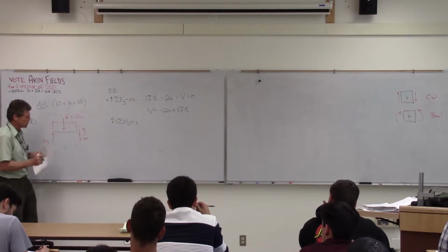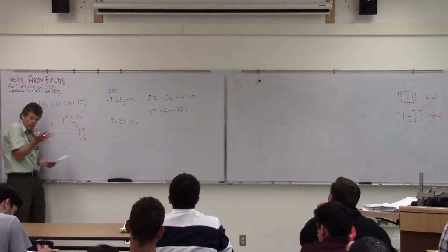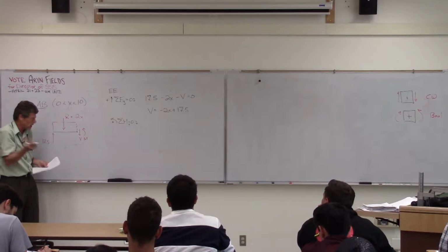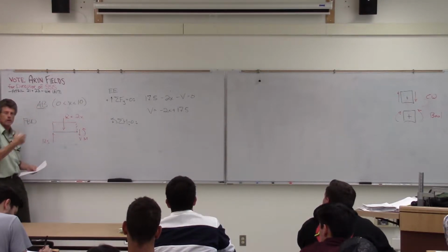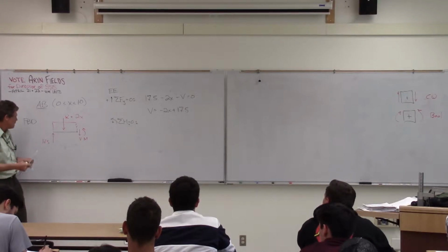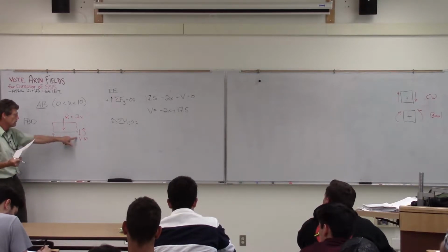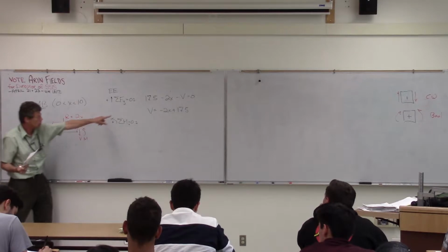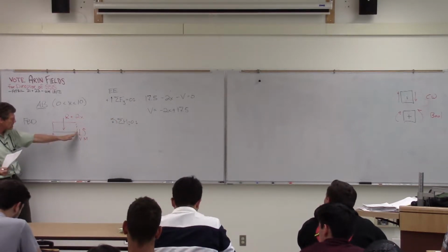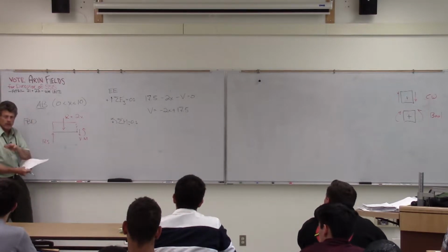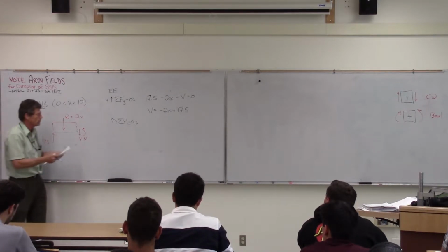And then we're also going to take our moment. And I suggest you can take moment anywhere. You'll get the same equation wherever you take it. It's generally easier to take it at point x because then the shear doesn't come into it. If I did it over here, which is fine, then I better make sure my calculation for shear is correct because that's going to enter the moment equation there. So generally we take it there, but again, moments have to be equal to 0 everywhere. You can take it wherever you want.